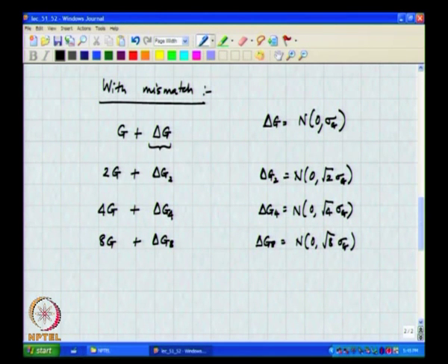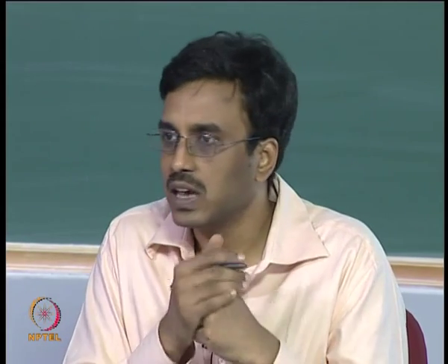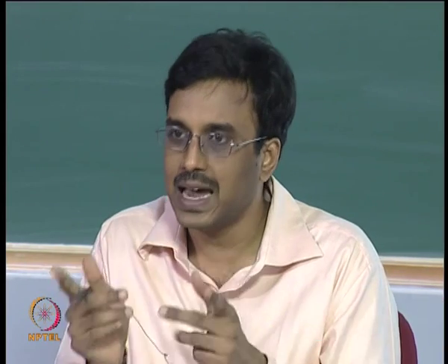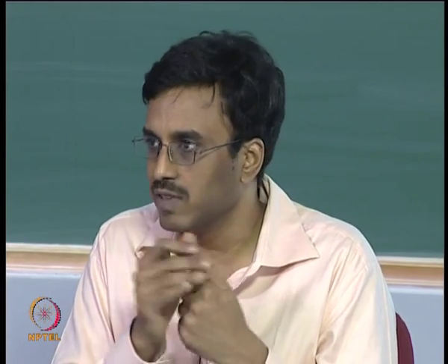Okay. So now let us look at the step size. Clearly if the individual currents change, it means that the DAC characteristic will also move from its ideal value. The step size will now differ from the ideal G times Vref that we had earlier. Whenever the code changed by 1, if the elements were all exact and were what we wanted them to be, a change in the digital code by 1 should cause a change in the current by G times Vref.